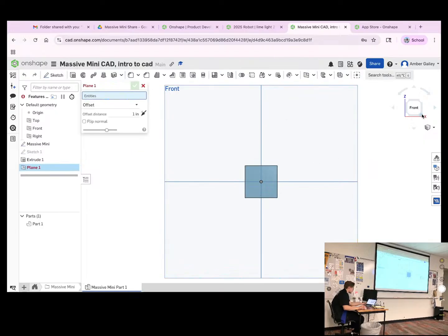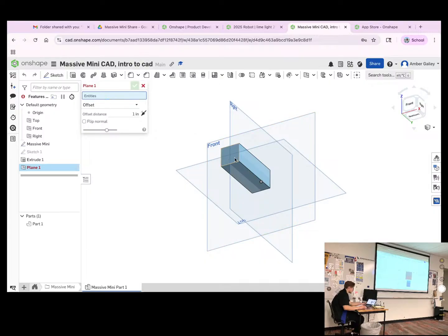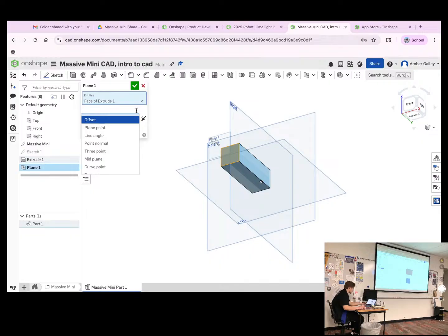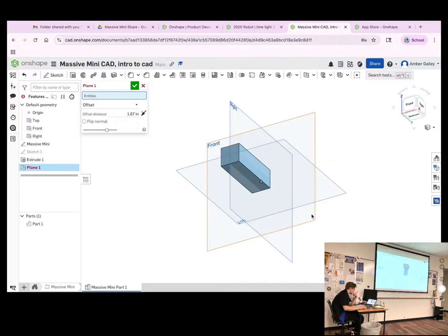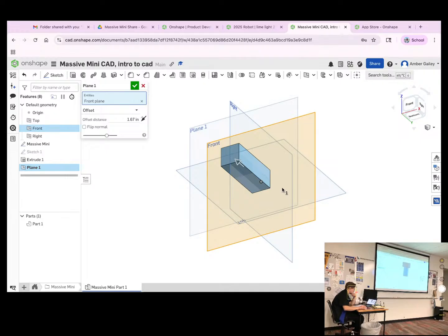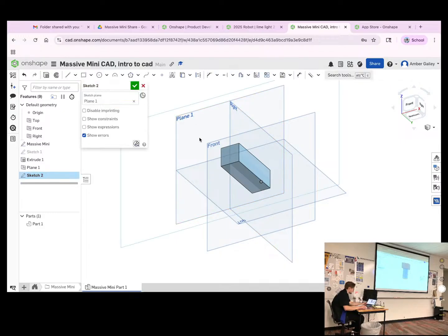So if I have another part above, here's what I'll do. And I want to choose up to next real quick. What's going to happen is that if I have a part that's going to intersect later on, my extrusion is just going to go all the way up until it hits that top part. So unlike blind, which is just going to go up as much as I say it should, up to next is going to go up to the next part.